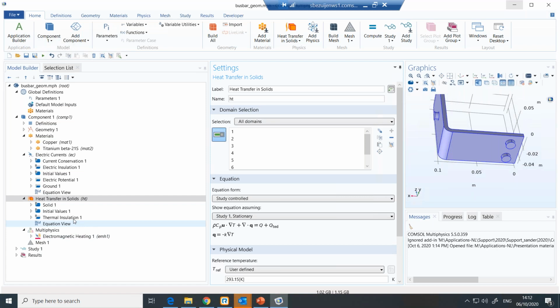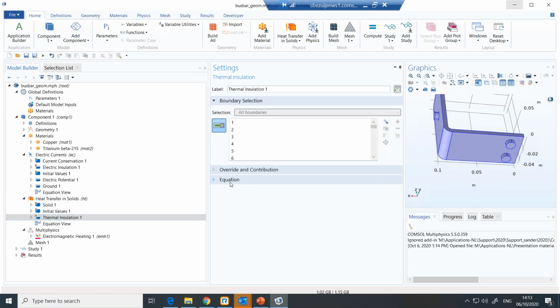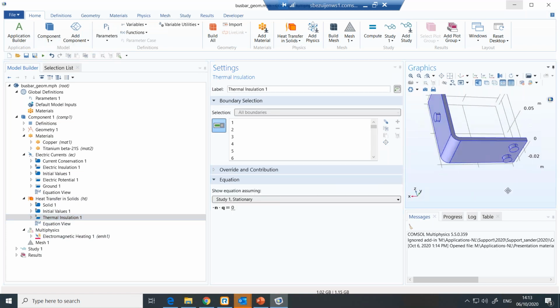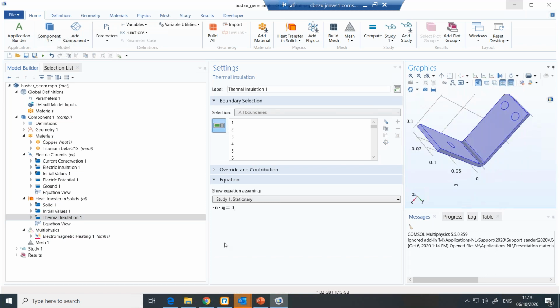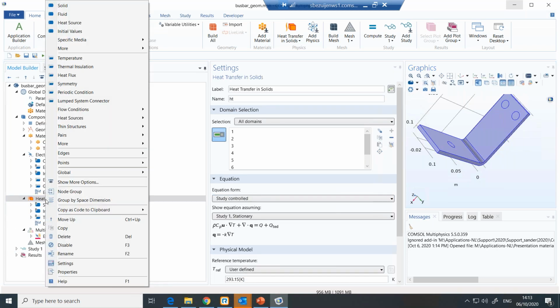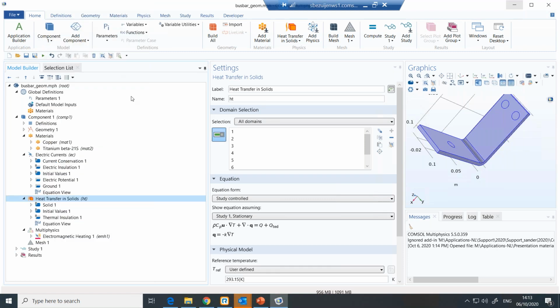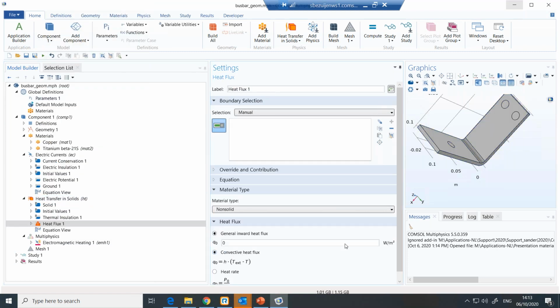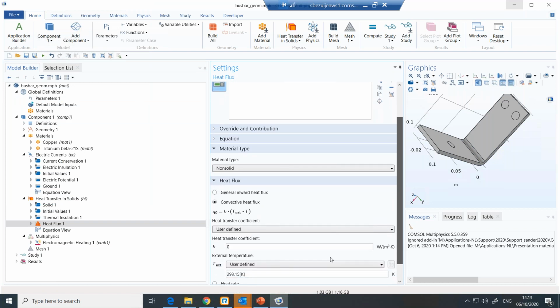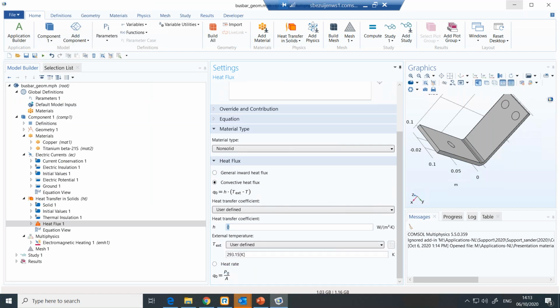What we need to do here is again check our boundary conditions, which state that this thing is so-called thermally insulated, and that seems to be the case because all normal heat flux is 0. And that actually is not what I want, because I want to go to a stationary case where there is some cooling occurring on the surface. So I'm going to call for a heat flux boundary condition, and more specifically a convective or a Newton's law cooling boundary condition, where I'm assuming that this whole complex behavior of fluid flow and cooling is all captured in this nice coefficient.